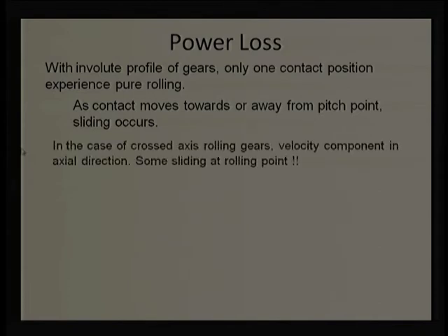Then another example was given: the case of crossed axis rolling gears, where the axes are not parallel, they are not intersecting, they are not coplanar, and they are out of the plane. Naturally, there will be some component in the third plane or third direction also, which is going to create additional sliding. That is why in the case of crossed axis rolling gears, a velocity component in the axial direction will occur, and that is going to increase the sliding. Overall sliding will increase in those situations.